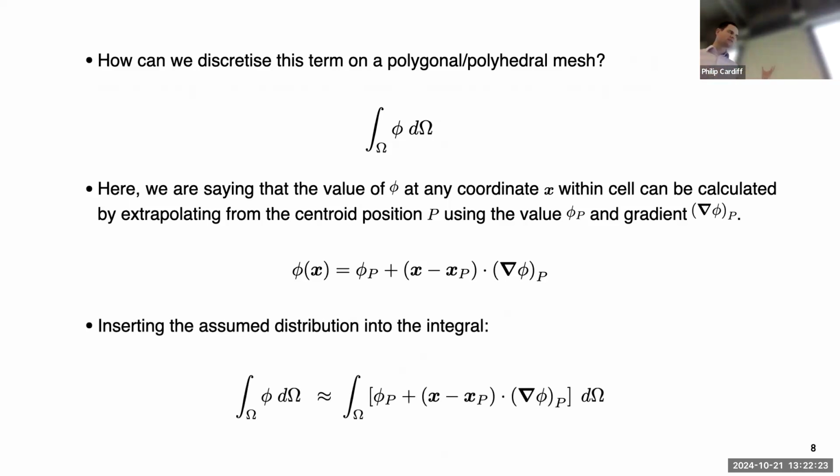This is going to make a second order finite volume method, but if we include a square term, that would be equivalent to quadratic elements. A cubic term would be like cubic elements, etc. So you can make higher order finite volume methods the same way you can do it for finite element.